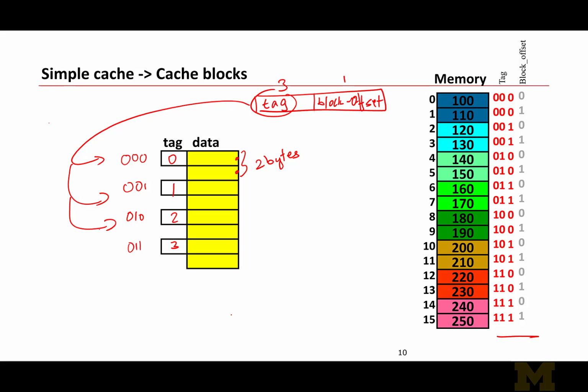4 of those tags. And if you go back to lecture 17, we talked about a structure called CAM, Content Addressable Memory, that is capable of performing these parallel comparisons. While we have the capability to do it, there is a limitation to how much we can scale the structure. So when you increase the size of the cache to, let's say, a few kilobytes, then the number of tags would grow proportionally to the number of cache lines.